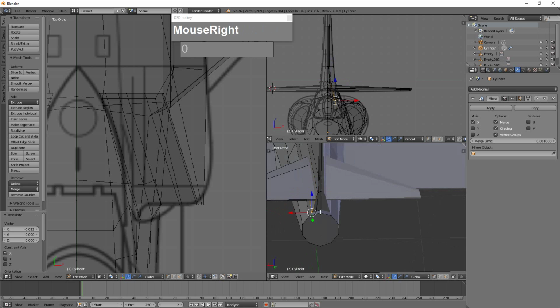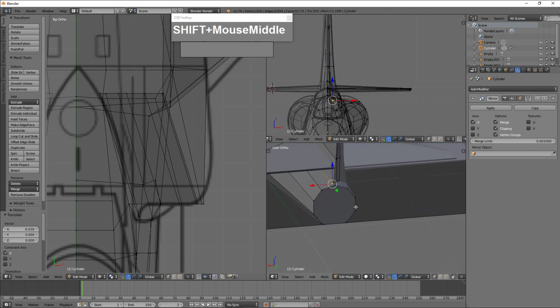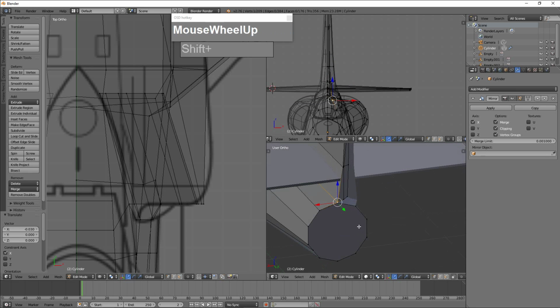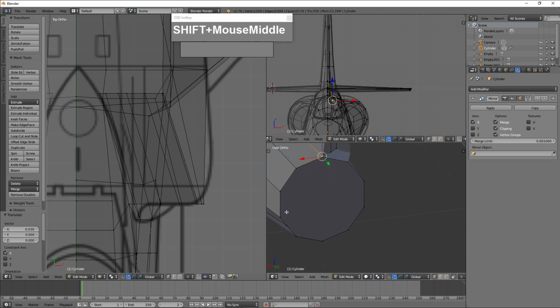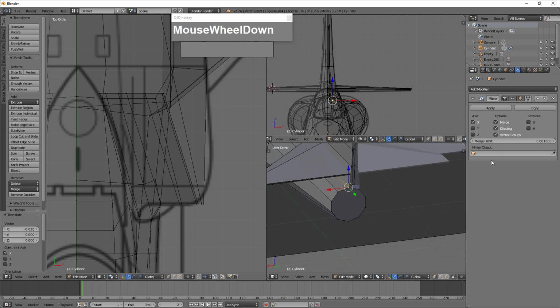Okay, I never have a chance to really use the loop tools, but I'm going to try to use it now. Right now here, because of the extra edge loop, it is not really distributed round enough. So for now, I'm just going to apply the mirror. I'm going to go to object mode, apply the mirror so that both halves are now stuck together.